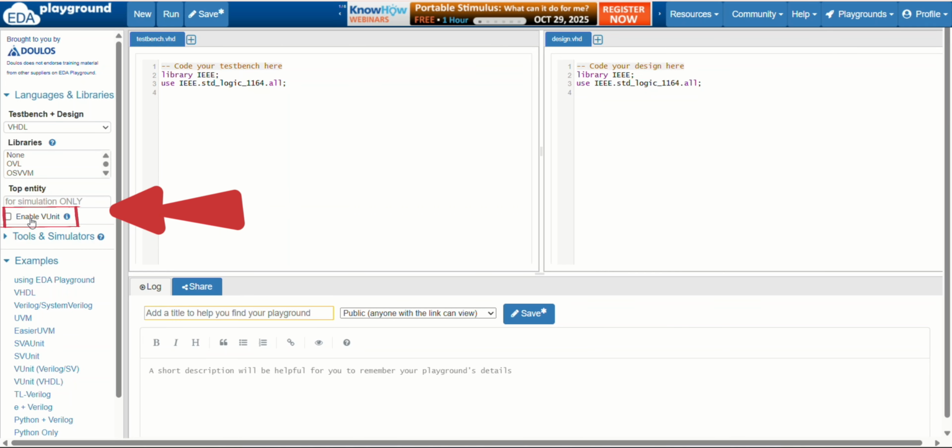So do you think you have to enable VUnit or not? I suggest for now, if you are doing a basic AND gate or OR gate or anything basic, then you should leave it unchecked, because VUnit is a very powerful tool used in professional large scale projects where you might have hundreds or thousands of tiny tests to manage. So for learning the basics of VHDL, or learning how the simple gates work, the manual test bench is good.